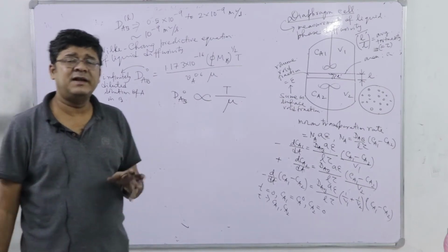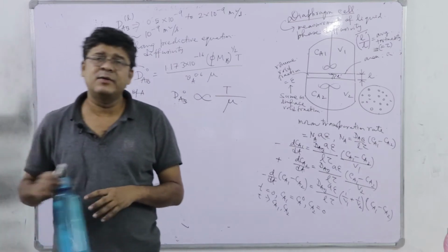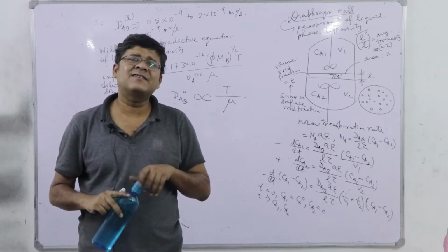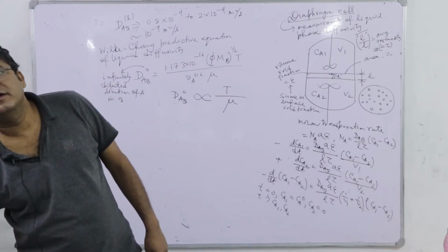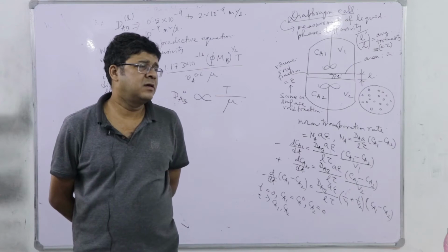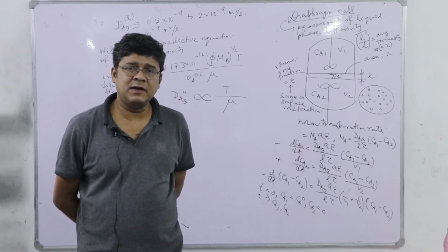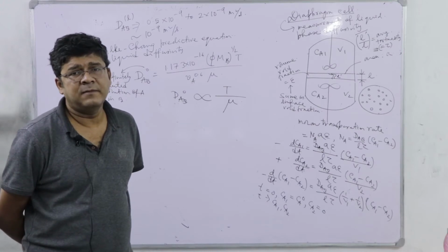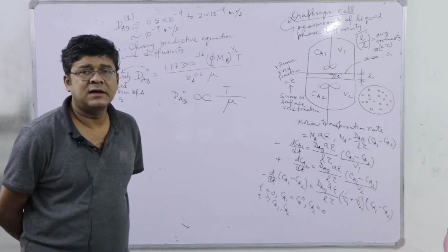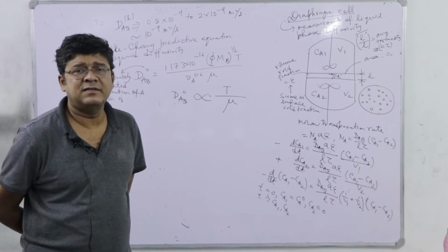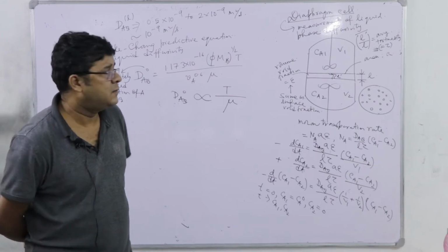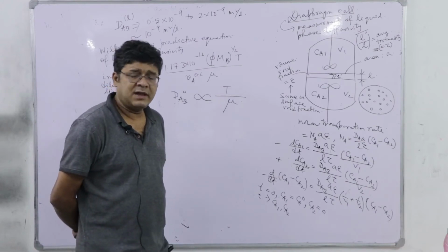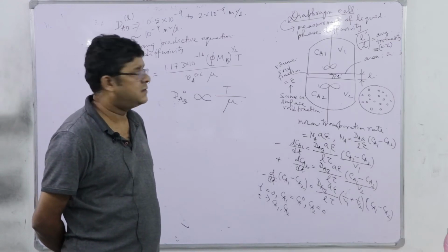So, that is because the liquid diffusivity is difficult, because the liquid phase itself is a phase which we less understand. Like gas phase, we have a model gas equation, that is ideal gas, and from there we can well document the deviation of real gas behavior from that of ideal gas, as we have discussed in thermodynamics. But in liquid, in classical domain, there is no ideal liquid model, right. It comes in statistical thermodynamics, but again there are debates. There is something called Ising model, which is in statistical thermodynamics, which describes something like ideal liquid, but that is beyond the purview of classical thermodynamics and we are not going to discuss this here.